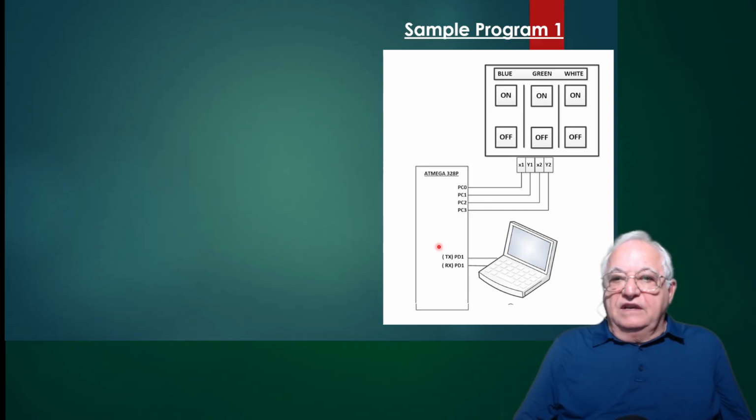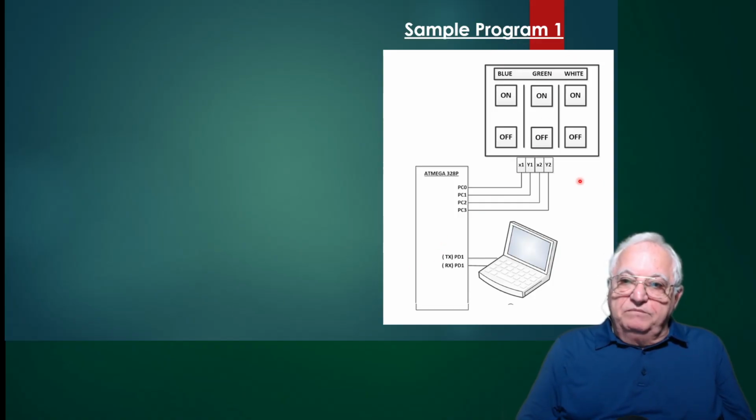Okay, so let's look at sample program one. We have a clear display. I pasted this picture behind the screen. No matter where I touch on the screen, I get a different voltage. So I'm just going to press with my stylus, go up and down through each of these squares, measure the output, and send it. The idea is that I want to get the boundary for each of these buttons.